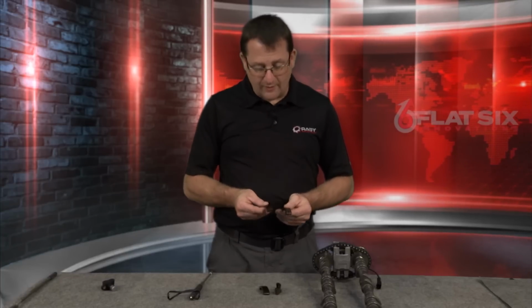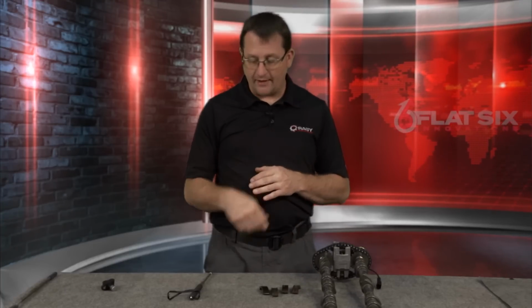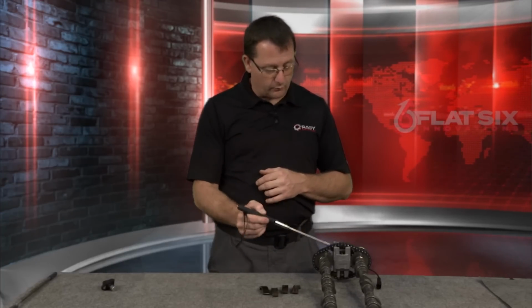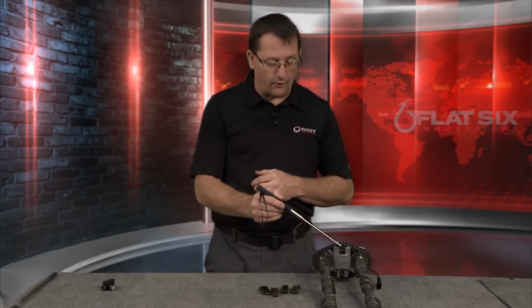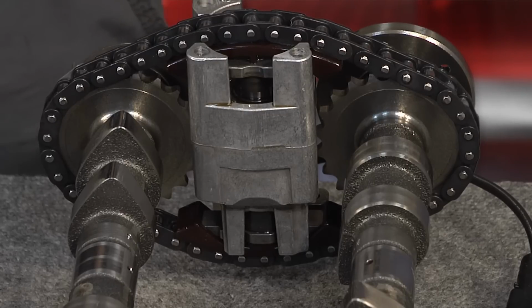So if you have a 5-chain engine, you have wear on these chain guides. These 4 chain guides we're talking about here, located between the intake and exhaust cams on both banks. You're going to have wear there. When you do your diagnostic, even if your car has 18,000 miles on it, you're going to find this out of range, okay? Case in point, I had a customer with a 2000 996.